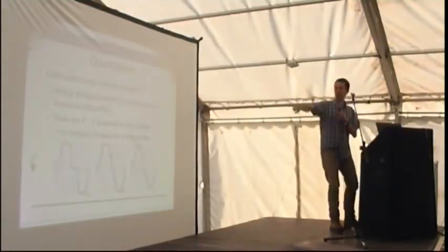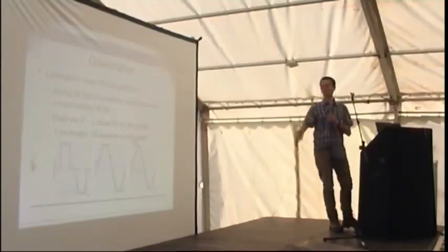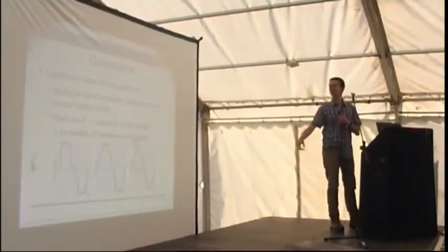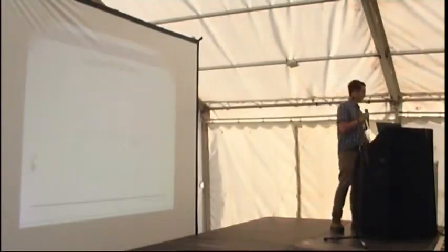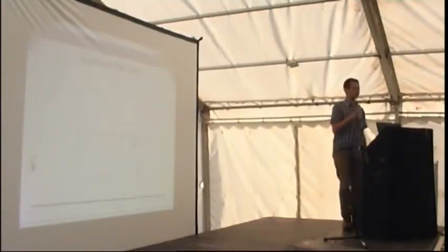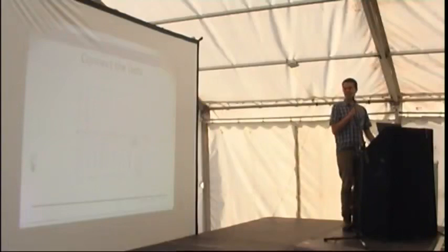For each timestamp, you have a value, and the more bits that you have in your analog to digital converter, the better the resolution that you get, and the better that you can figure out what the original signal was. So, more bits, better is the takeaway from this slide. And who can play connect the dots? What have we got here? Just shout it out. Sine wave. Looks pretty obvious, right? It's going to be that. Oh, wait, but it could be that. And it could be that.